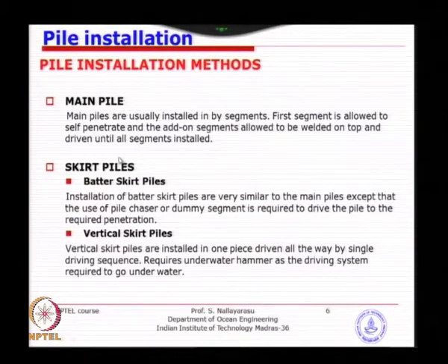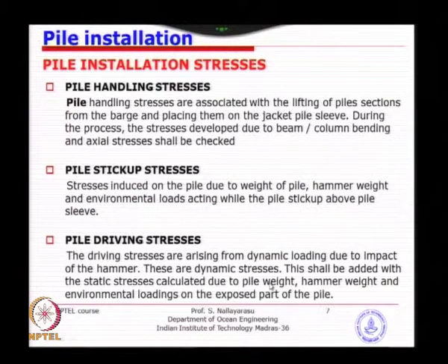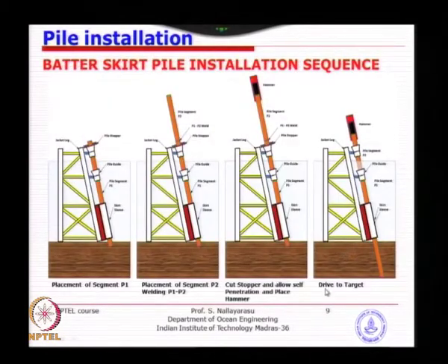Skirt piles, you have a batter skirt pile as well as a vertical skirt pile. I think some pictures will be there, we will see those pictures. So, the main pile I do not think you need any explanation, but the skirt pile you see here, in this case the skirt height is limited to the bottom, so that you do not need to insert the pile all the way from bottom to top, which is going to be a waste of material and driving time. So, you see here the first segment is inserted into the sleeve and the guides.